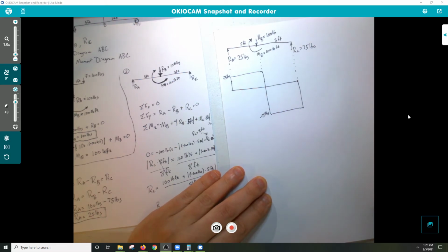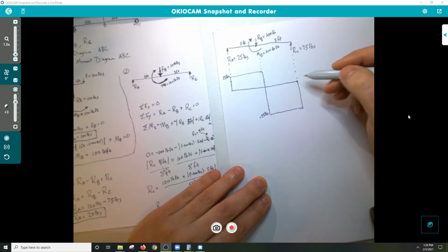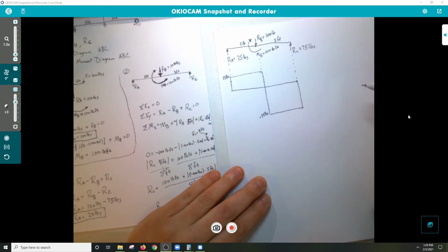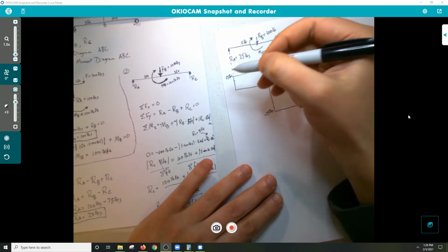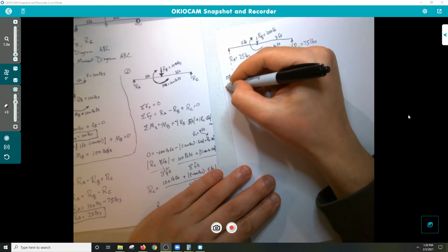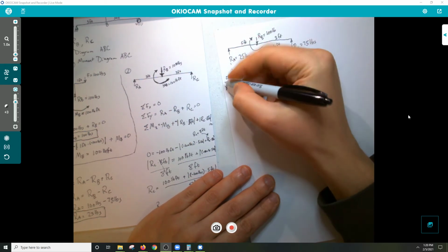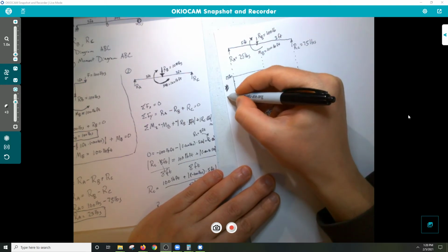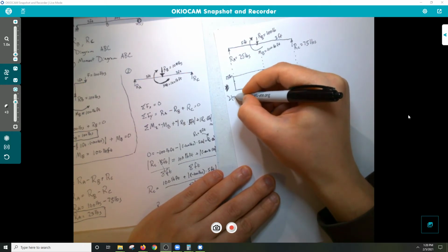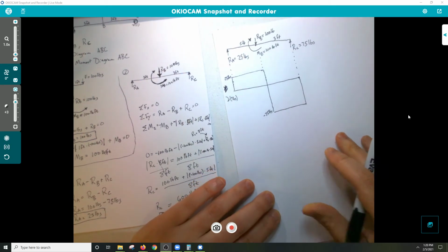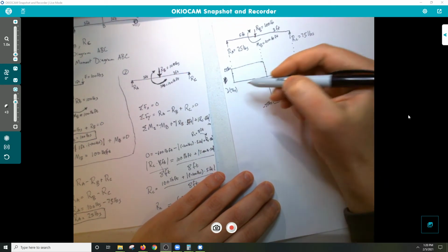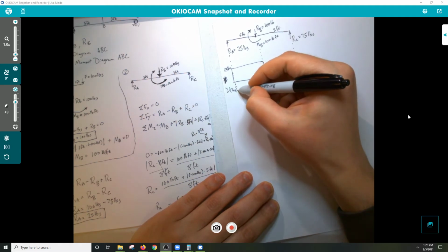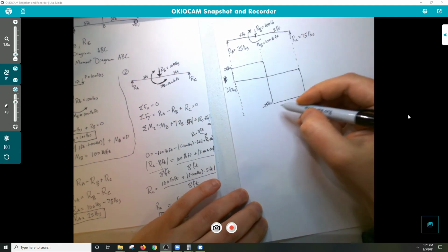So we know we've done that correct. We wound up at 0. If we're not at 0, we're not in equilibrium. It's not correct. The only thing I like to do for these is label it; that's supposed to be a V, shear. Shear diagram in pounds. And then our bending moment. Carry dots down.